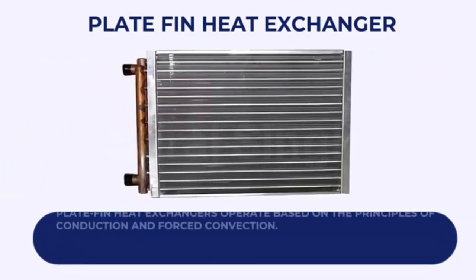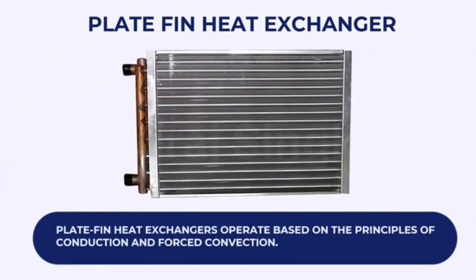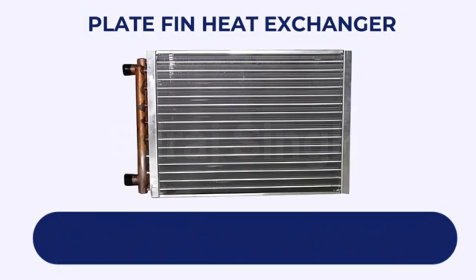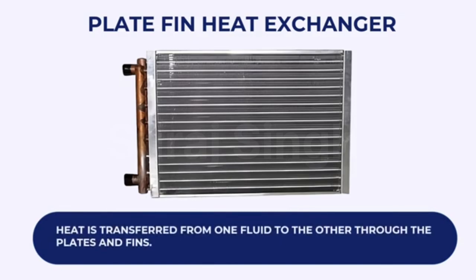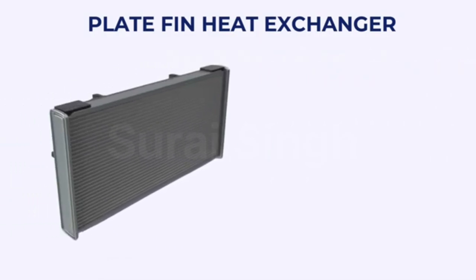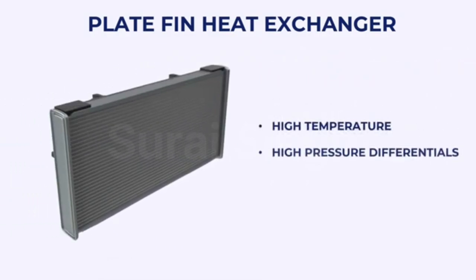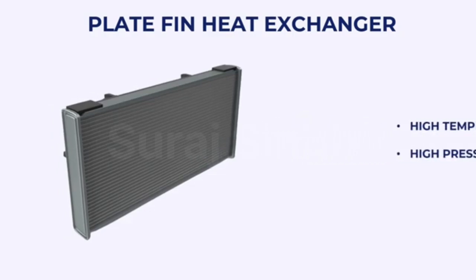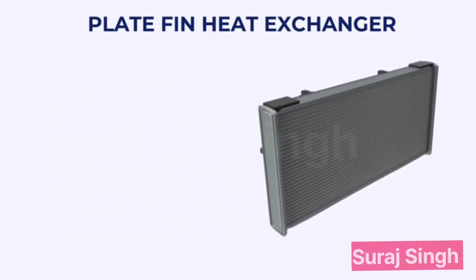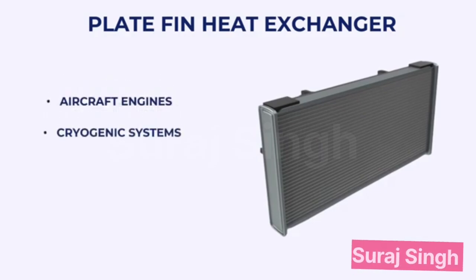Plate fin heat exchangers operate based on the principles of conduction and forced convection. As fluids flow through the channels, heat is transferred from one fluid to the other through the plates and fins. Plate fin heat exchangers are suitable for applications with high temperature and pressure differentials. They are mostly used in aircraft engines, cryogenic systems, and automotive.